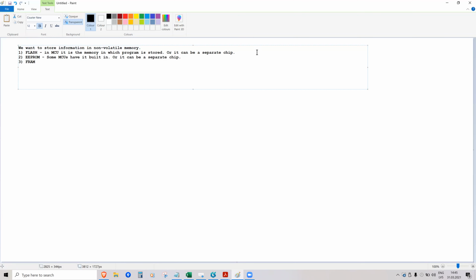So let's see. The flash memory, which is built inside microcontrollers, usually it can be erased and rewritten only about 20,000 times. Or I'll write erases. Some other flash memory maybe is more durable, but basically it has some rather limited number of erase cycles. As you know, solid state drives, which are very similar to flash memory, they also can wear out because they have some limited number of erase cycles.